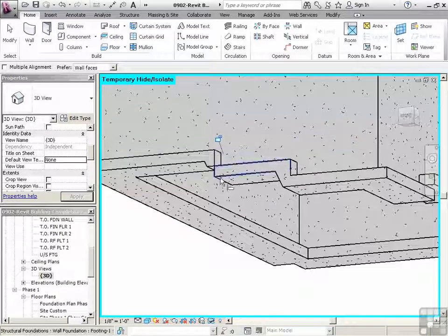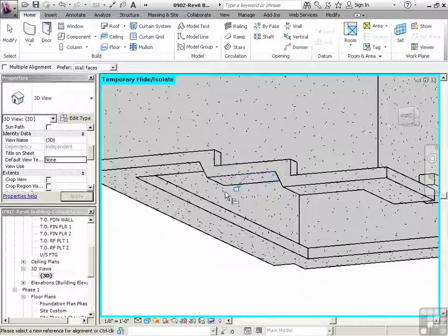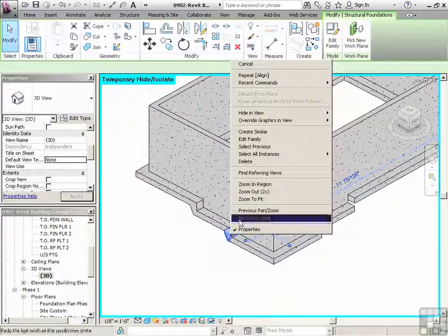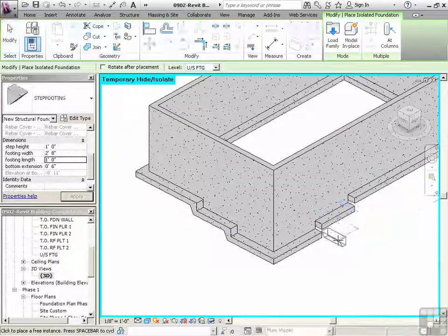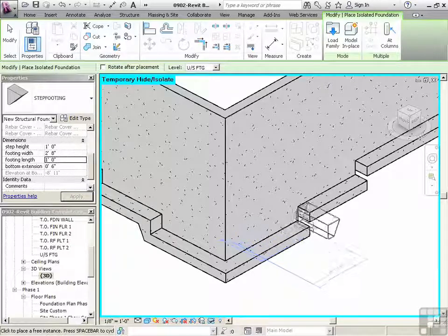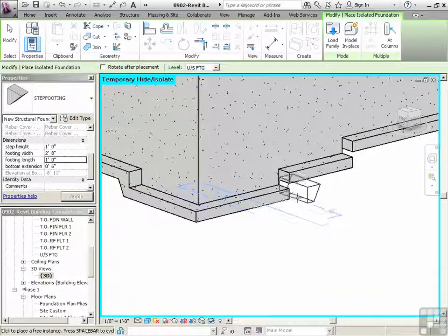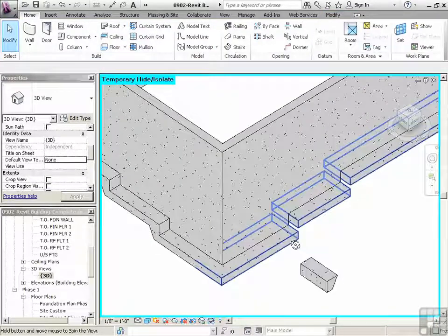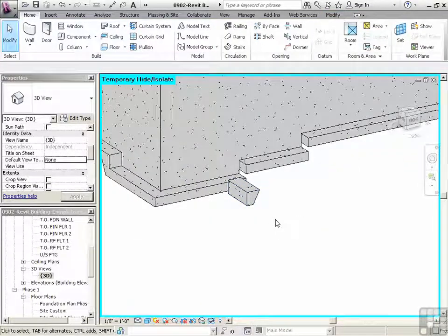I think we aligned down to the bottom. It seemed to work just fine. And then we could take this. Sometimes you can click on an object, say create similar, and then it just pops it in again. If we use the space bar while we're inserting it, we can just drop it in. It's very hard in 3D to get the right location. It looks like it may be right, but when you actually spin it around, it's quite different. So let's just do some aligning again.